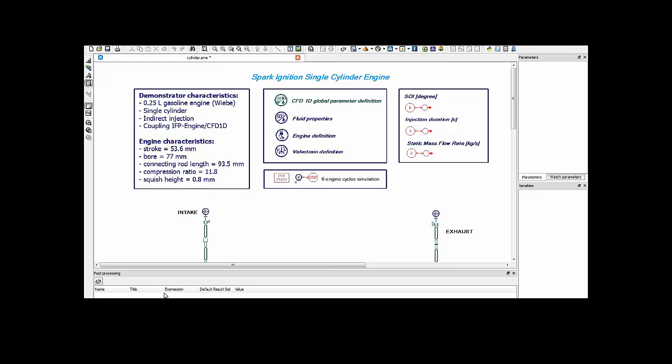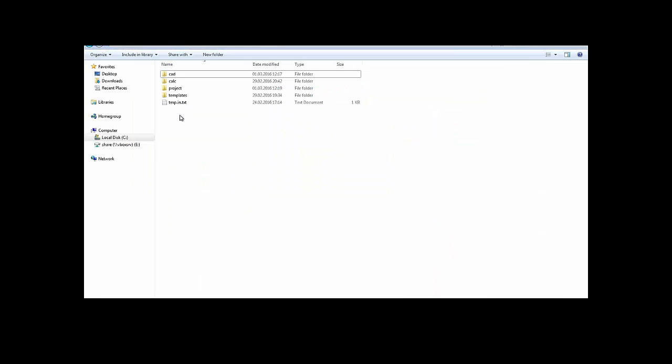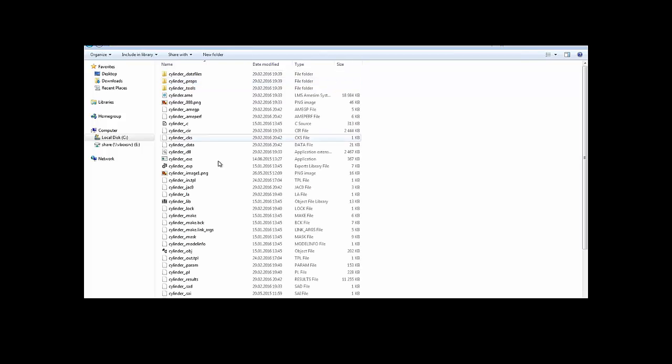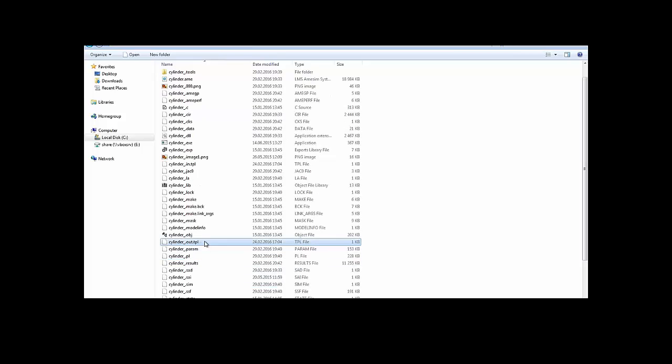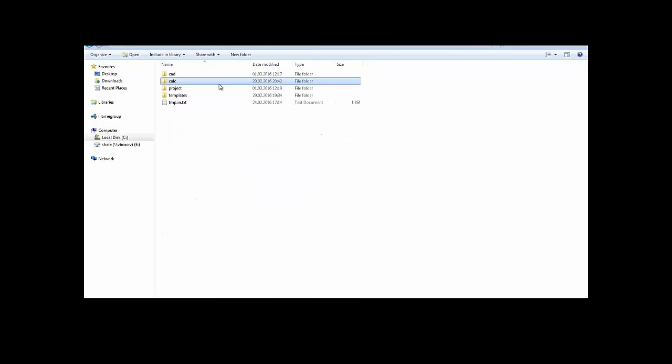After the setup is done, in the project folder of Amesim, we can find these templates for the output file with the TPL extension, and also a template for the input file. Here it is, it's also a TPL extension. We can take them to use in pSeven as templates for our text block to set up the integration.